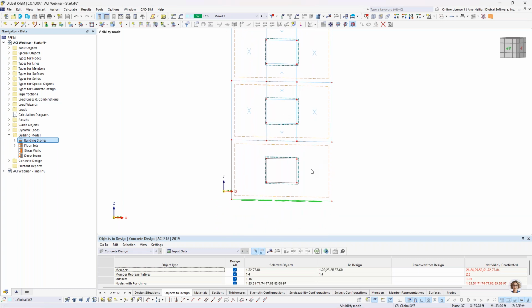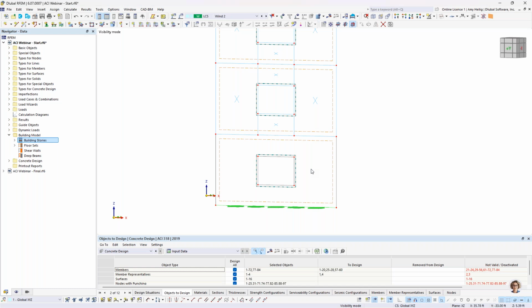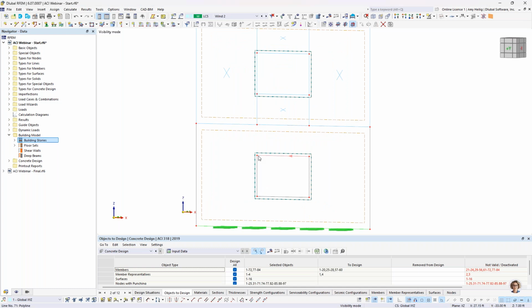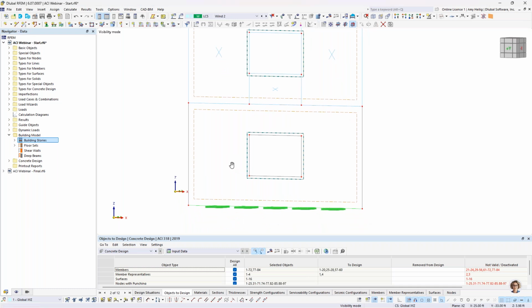Now for this first shear wall, you'll notice that I don't have those surface cells. So anytime that you have a shear wall with an opening, what we need to do in order to generate these surface cells is to actually create a line element that spans from the opening to the edge of the surface. Now, we certainly can do this manually with a new line option up here in our toolbar and just graphically drawing that line. But I'd like to show you a quick trick here.